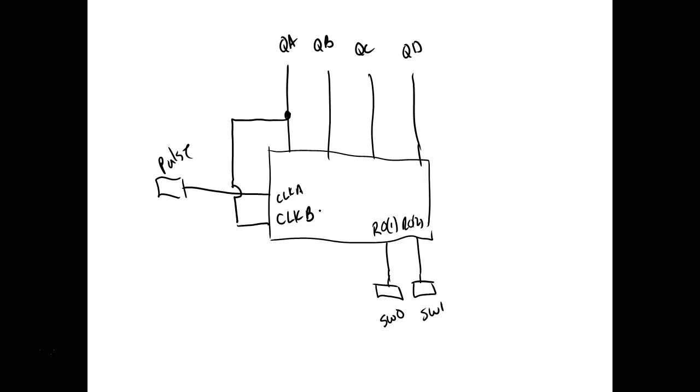So this is the circuit I have. And then of course I got power, which is VCC is on pin 5, and then common is on pin 10. So this is moved again, right? So that's what I was saying. When you get into your combinational logic circuits, make sure you look at the pin out on where these powers are connected. All your basic gates, they're always on the upper right hand side and the lower left hand side, right? But on these combinational gates, they're sometimes in the center, right? You understand that?